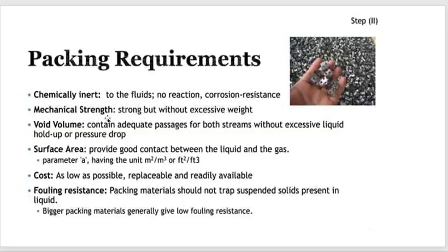Mechanical strength will prolong the time of using this packing, and also the void volume, because this is your tool to make liquid vapor contact, and you want to maximize this contacting and maximize the surface area. Also the surface area provides a good contact between the liquid and the gas. Okay, the cost: you can choose packing with higher cost or low cost, depending on the corrosivity of the liquid and the vapor, and the reactivity of the liquid and the vapor with your choice, if it is from plastic, from metal, from ceramics, or something like that.